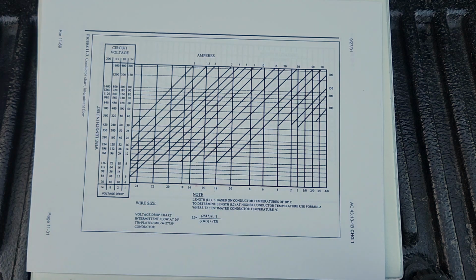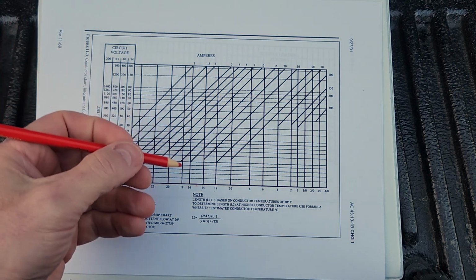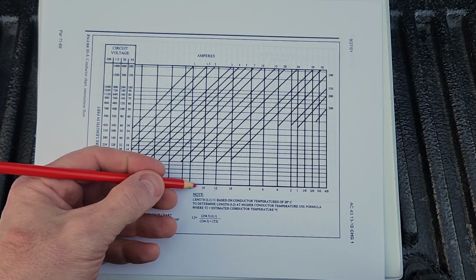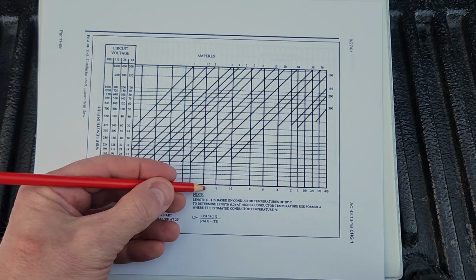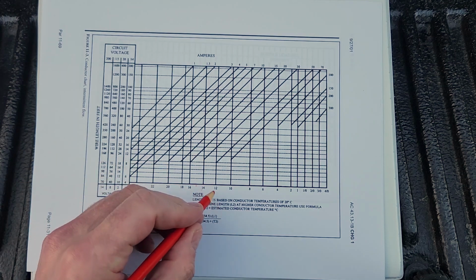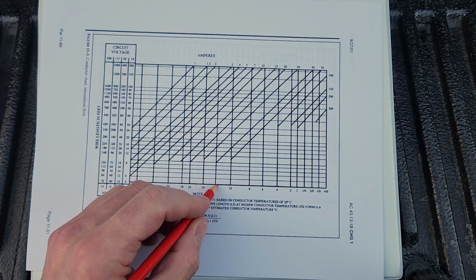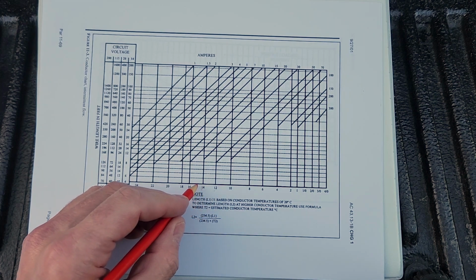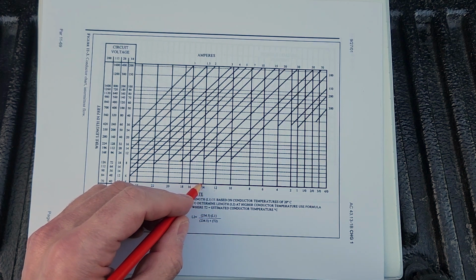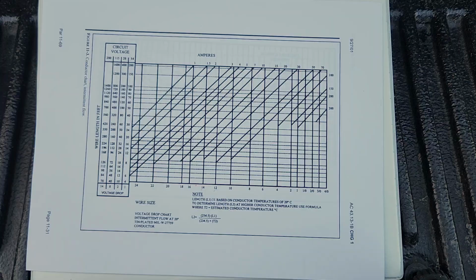Yeah, so nobody sells 15 gauge except maybe the Chinese, and you don't want to buy that stuff. So you go to the next largest wire size, which is 14. So in the previous example, with a continuous load of 20 amps, you had to go to 12 gauge. If the circuit's only intermittently loaded to 20, you can get away with 14 gauge.